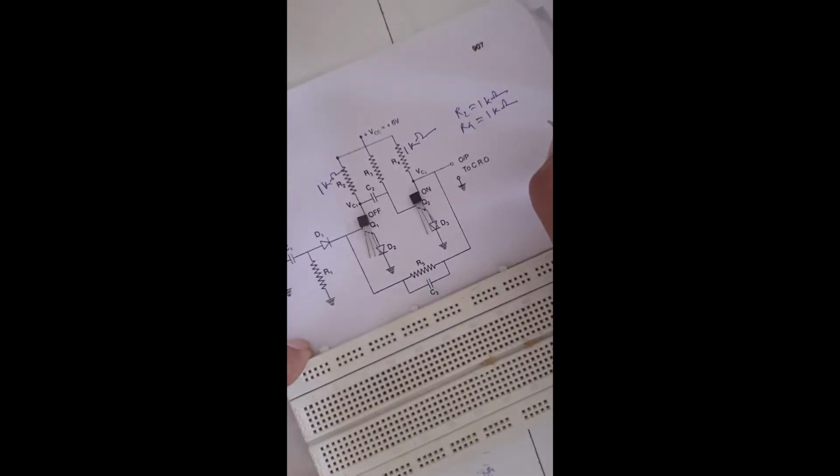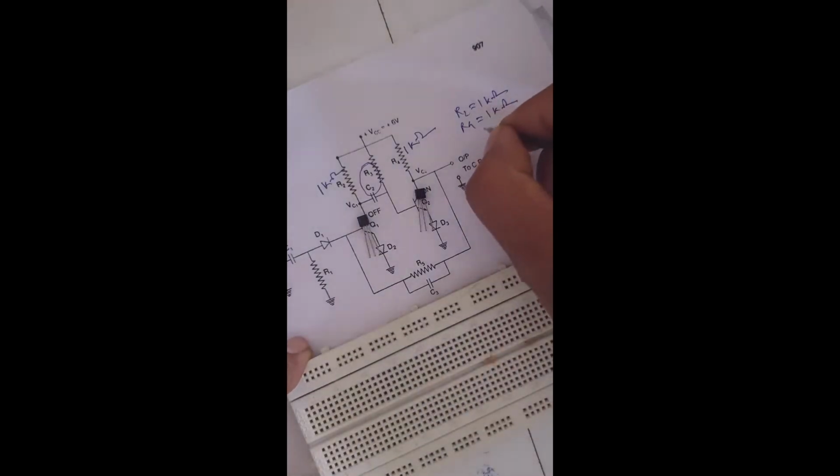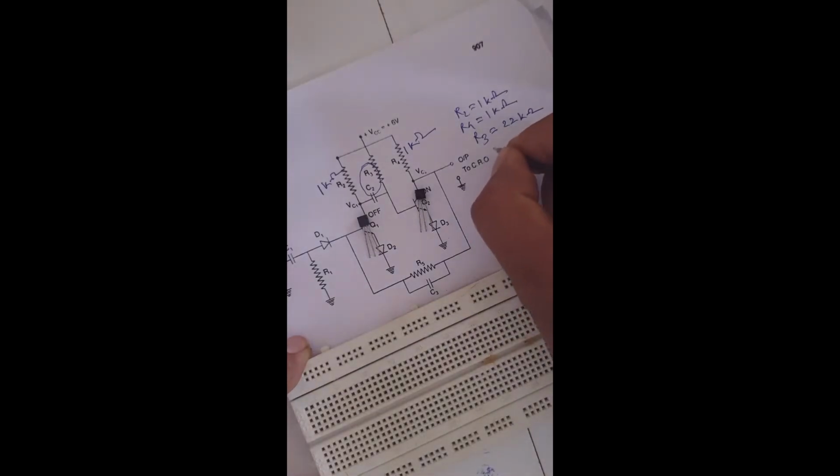Then our RC combination is this R3 and C2. So for R3 we have a 22 kilo ohm resistor. R3 we are taking 22 kilo ohm resistor, and C2 is of 4.7 nanofarad. C2 we are taking 4.7 nanofarad,